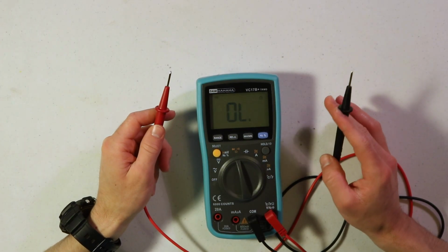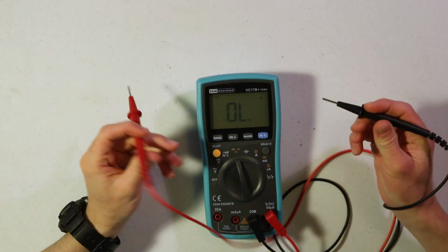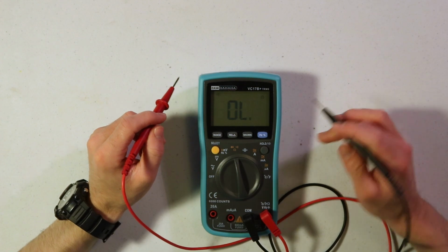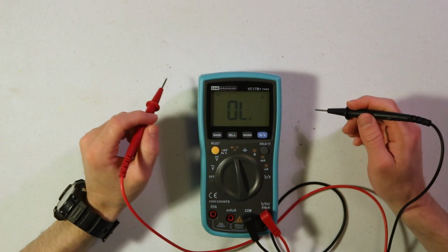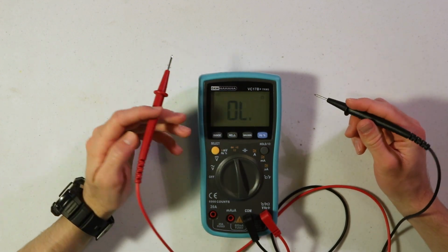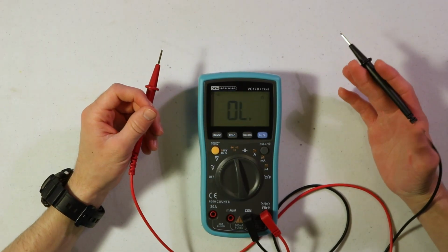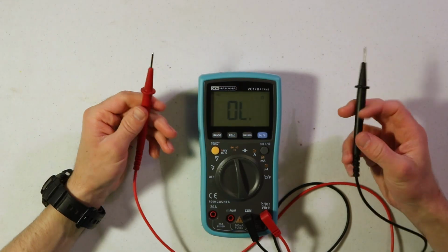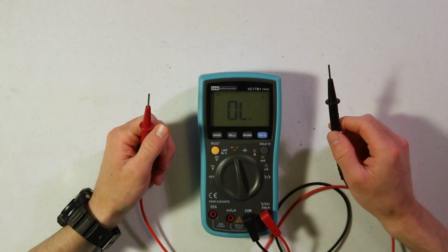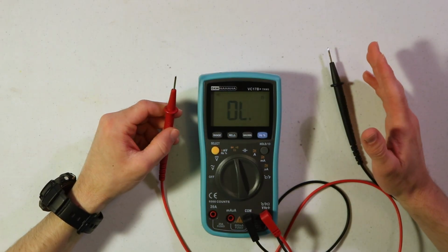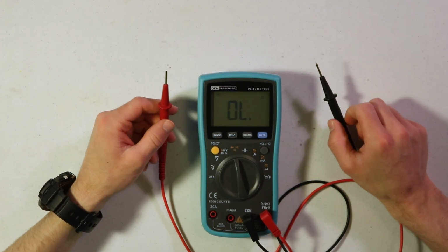If you're not sure if something is working or not, then just use your continuity probes, touch it here, touch it there, and see. If it was supposed to have a connection between there and it doesn't, then something's wrong. But if it does beep, then you're good. That may not be where the problem is. You just move on to the next part. So this is a really useful tool when you're trying to debug a circuit and make sure that it's working, which you're likely to encounter at some point, so just keep that in mind.